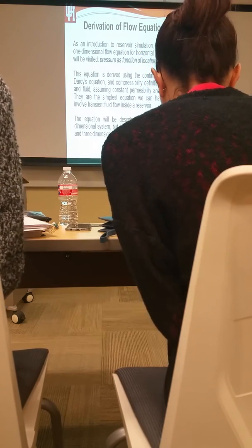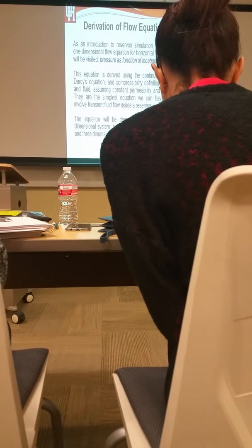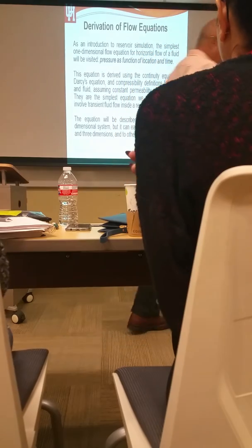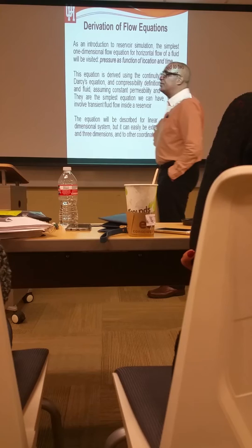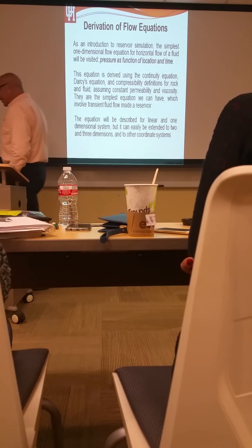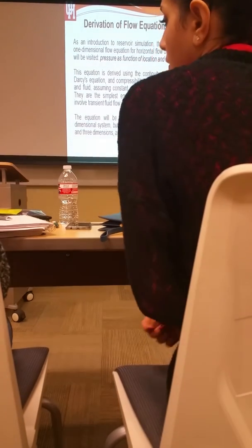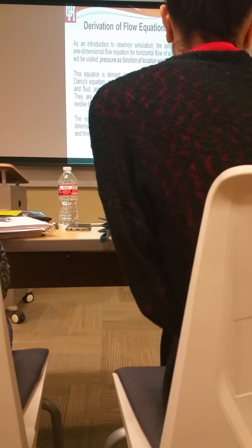H-E-A-T. Heat equation, right? It's well known as the heat equation, but it can also be used for describing the pressure distribution in a reservoir. Even more, all the well testing theory developed is based on this heat equation, but instead of heat being represented as the variable, what is represented as the variable is the pressure. Pressure as a function of space and time.